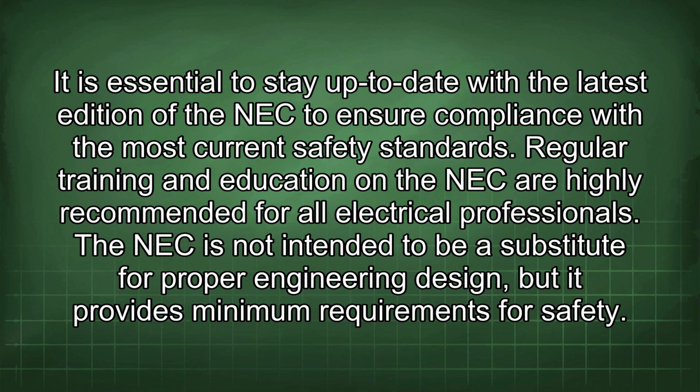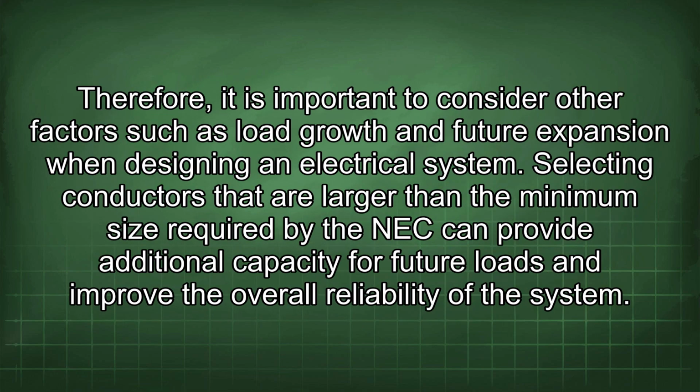The NEC is not intended to be a substitute for proper engineering design, but it provides minimum requirements for safety. Therefore, it is important to consider other factors such as load growth and future expansion when designing an electrical system. Selecting conductors that are larger than the minimum size required by the NEC can provide additional capacity for future loads and improve the overall reliability of the system.